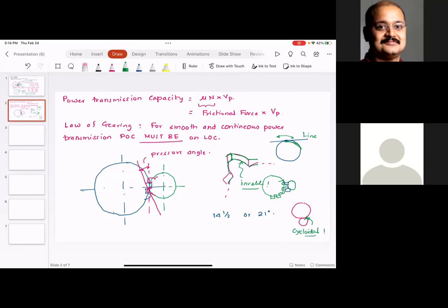So the cycloidal profile is the ideal profile for gear transmission, because the two gears coming in contact and disengaging is basically like one small wheel rolling on the big wheel. But at the bare minimum, you can assume an involute profile and have a line roll on the circle, and the curve traced by the point on the line is nothing but the profile of the gear.